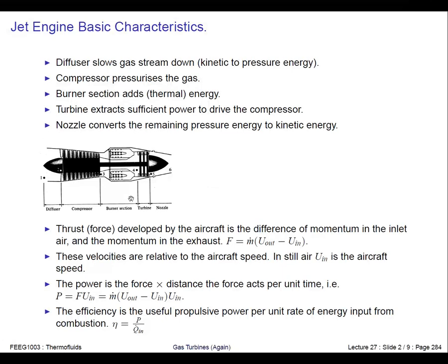In a jet engine, effectively what you want is the turbine to be as small as possible. In fact, so small that all it does is power the compressor. And what you want to create is lots of excess enthalpy at the exit of the turbine, because this is used to go through a nozzle and produce thrust for the aircraft.